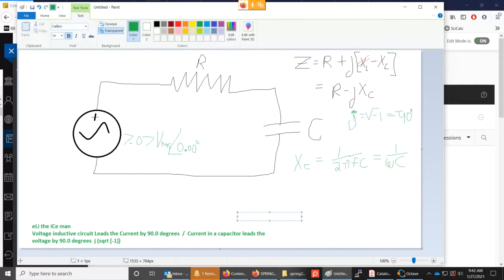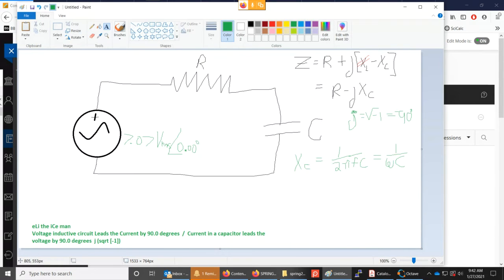And so, like I say, with mathematicians, they say, oh, well, it's imaginary. Well, in physics and electrical circuits, it's not actually imaginary. It indicates that there's a 90-degree phase shift, meaning that the sine wave of your current is 90 degrees behind the sine wave of your voltage, or if it's inductive, you know.